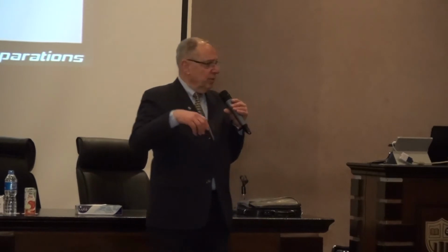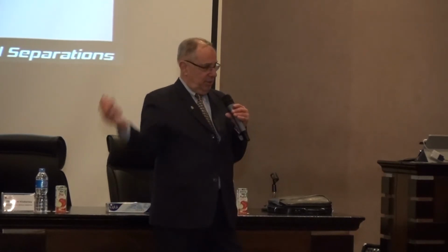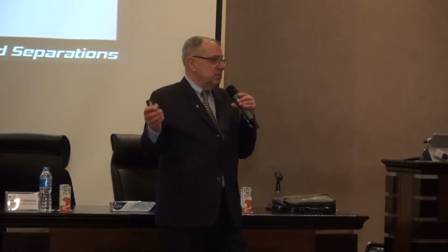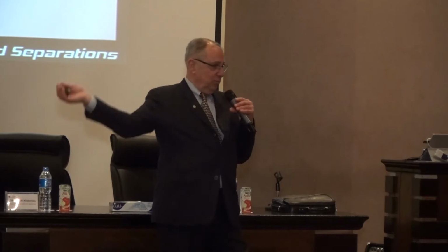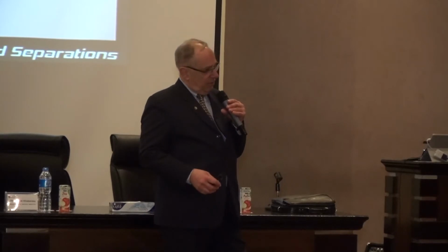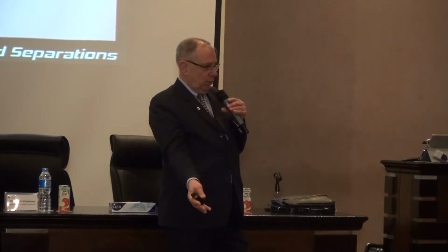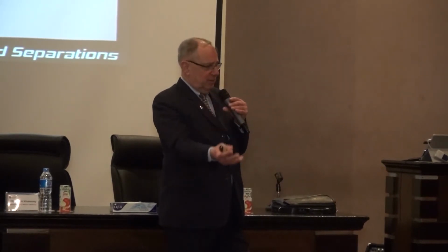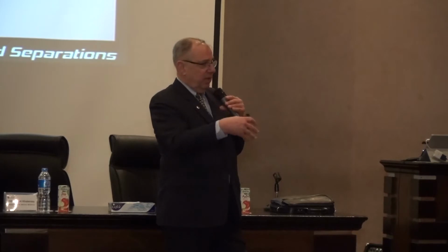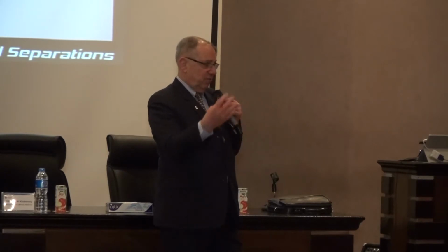Then you also have to deal with the length of time it takes to depressurize. You just can't open the vessel. If you just open the vessel like this, that is like having a sonic boom. So there is some depressurization. And then there are some engineering considerations with the depressurization: this will cool and it will ice up. So you've got considerations having to do with the cooling, what's called the Joule-Thomson effect. You have to have engineering to ensure that when this cools, you have enough heat so that you don't get freezing.